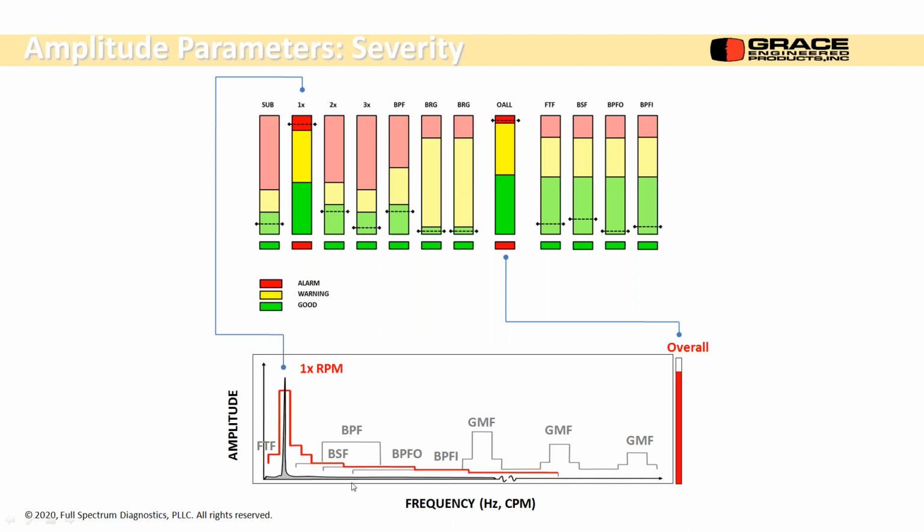This is another suggestion. There are different frequencies that are bound to show up based on the design of the machine. So there's 1 times RPM, there's blade pass frequency, there's gear mesh frequency. You're popping up a packet of overall energy information from this chart, basically every second, every time you collect data off your machine. And it comes up as a kilobyte package or whatever into the cloud. There is a way you can probably do that with each frequency you're interested in.